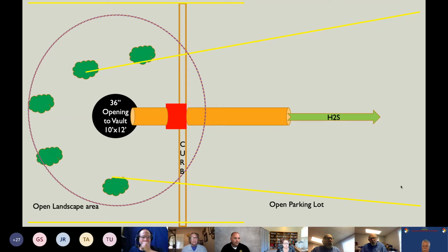They're both bad. So what we had to do is set up a fan, and the properties tell us that we're going to put this fan on exhaust. Sometimes people would put it on supply, and I'm not going to go into a ventilation profile on this, but we decided to do an exhaust, which is going to pull those heavy gases out and push them into an area where we don't want them and push it away from where we're operating.